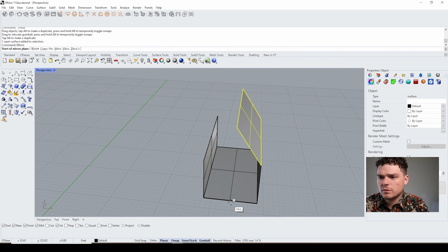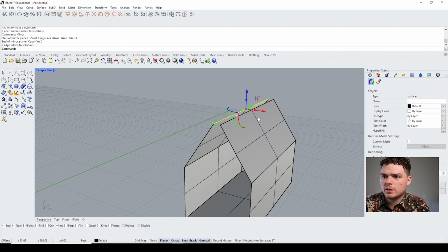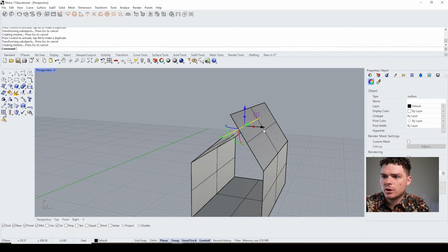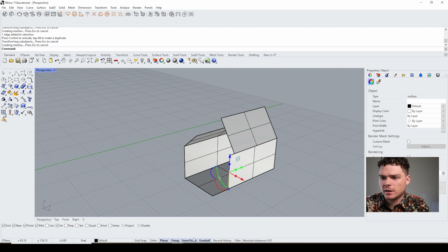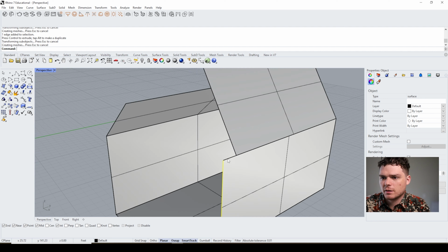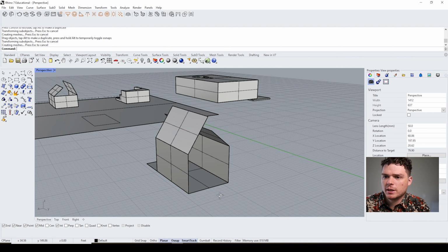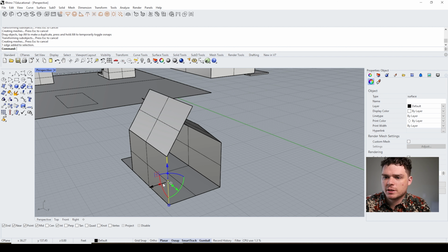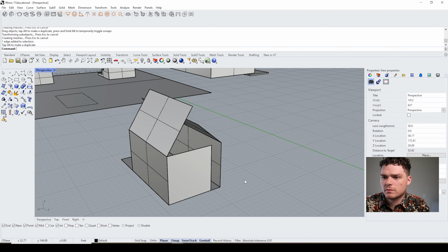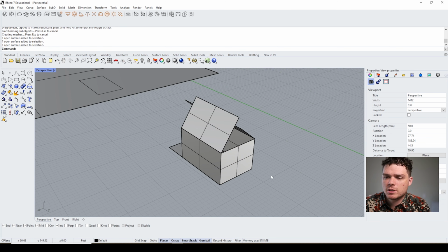Using the mirror tool, I'm going to mirror this, and again, maybe you want to do kind of like a sawtooth roof thing. Maybe you want to have this dynamic porch where you're kind of pulling back an edge and creating a porch here. Let's turn on gumball. And you can see that pretty quickly here. I can Control Shift gumball an edge, and if I wanted to just cut this off, I could actually just extrude a new piece and then hit snap, and you'll notice it is a separate surface.